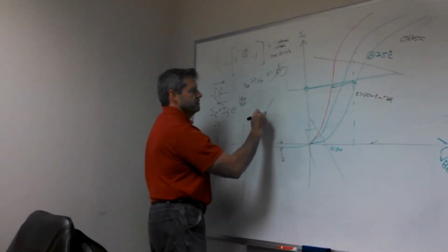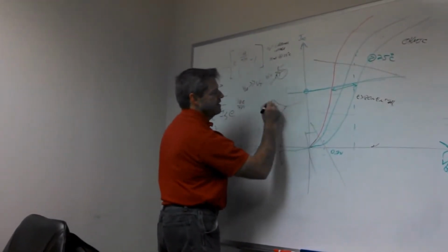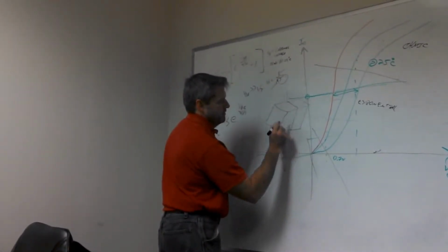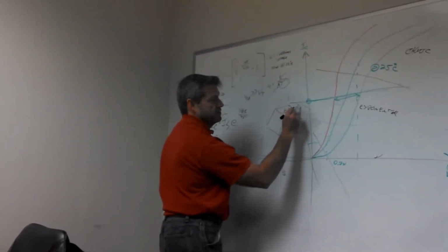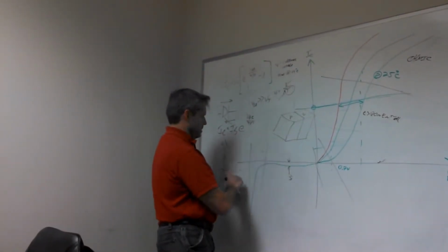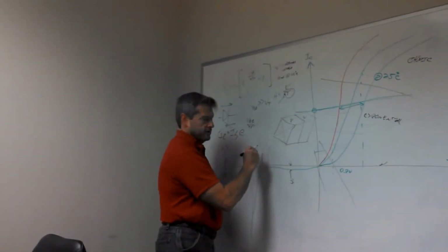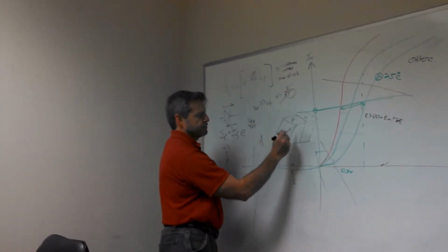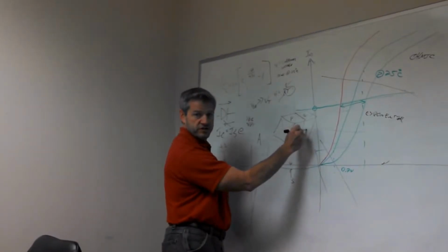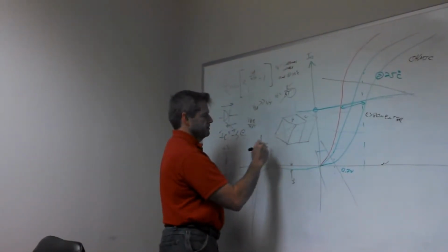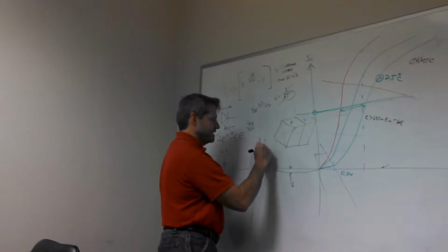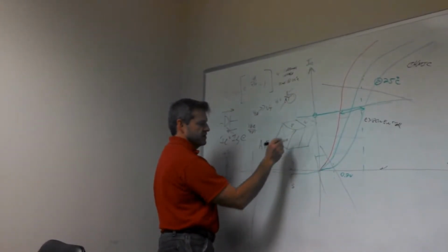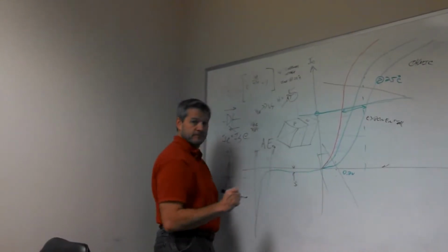IS is a function of, if you look at the diode as a block of stuff where this side is doped P and this side is doped N, the cross-sectional area A. It's a function of the doping concentrations and the band gap, and in here somewhere is the temperature.